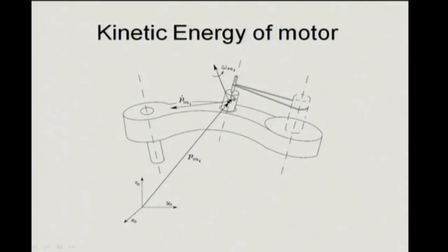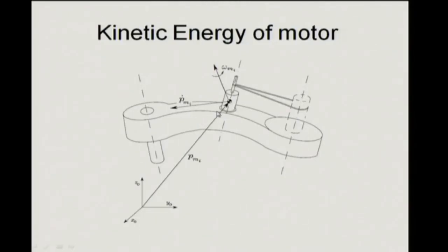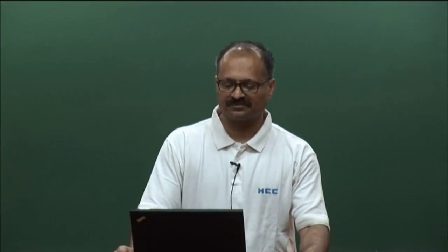So, this spindle internally becomes a much larger structure with a diameter, and this could be, I mean, this is a belt shown schematically, but there will be a reduction factor between here and here, and this need not be located at this joint either. It can be located at a location which is other than this joint axis physically, and it may not be halfway down to the other joint, but could be in proximity, but could be off center. Okay, and there is a reduction drive and coming off the other side.